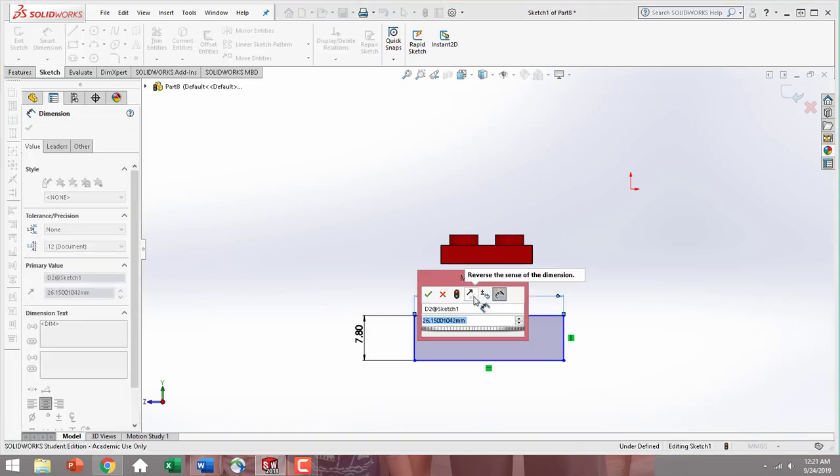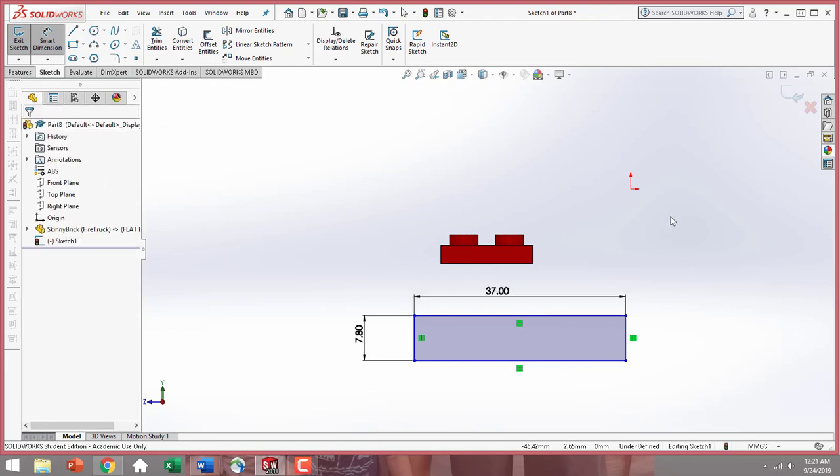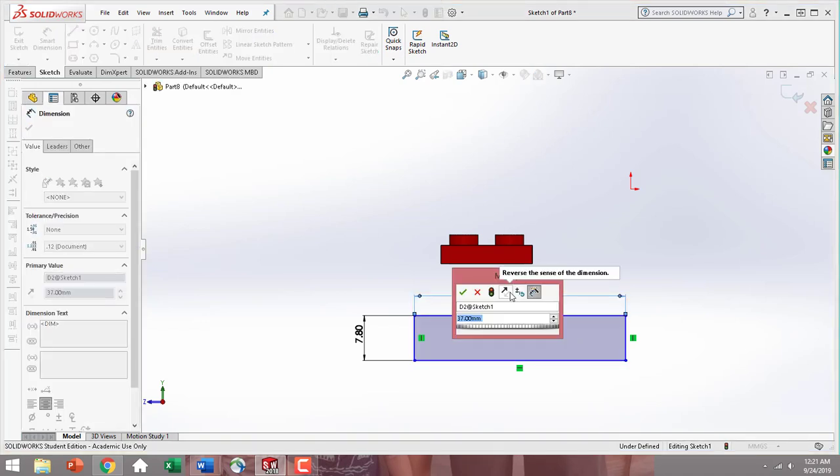So once again, make sure you've zeroed out and go ahead and measure the width of this. If it seems off, it probably is. So make sure you measure twice. So I'm still getting about 37 millimeters. Then hit OK. Now, we have all the relationships and dimensions we need, but our rectangle is just floating in space basically. So to fix that, we need to attach it to our 2x1 brick. This is actually going to be probably 32.